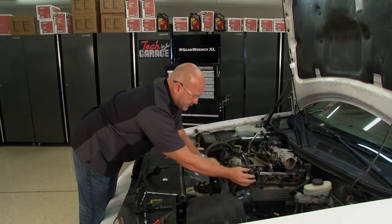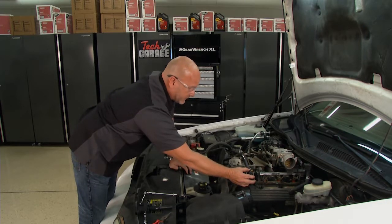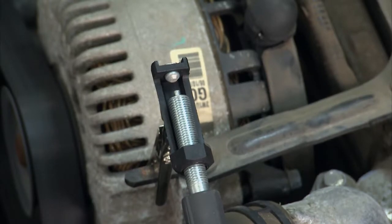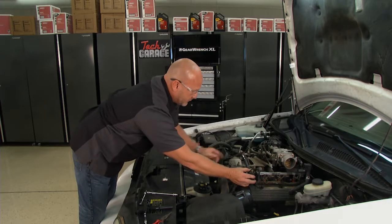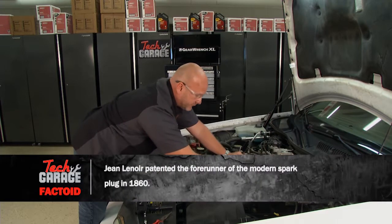Now you can hold it at this end and support it, and here's where you need a buddy. Hey Chase, go ahead and crank it over and let's see if this is sparking. We got no spark. You can kill it, thank you. We got no spark jumping that gap. We've got a problem with coil pack number 5.